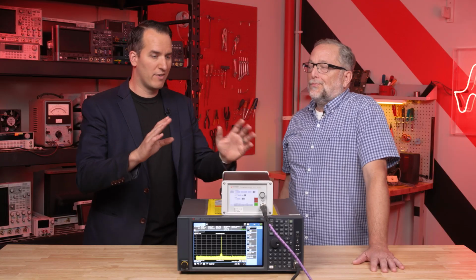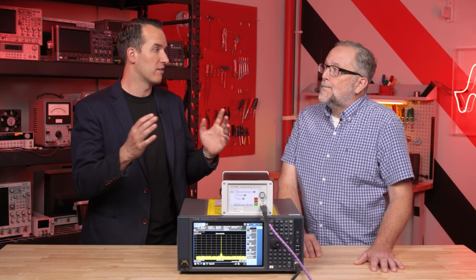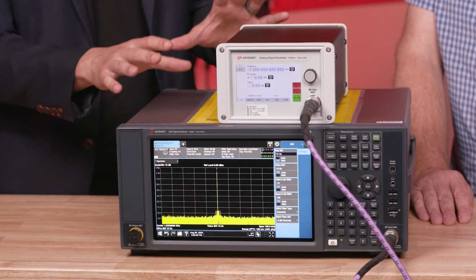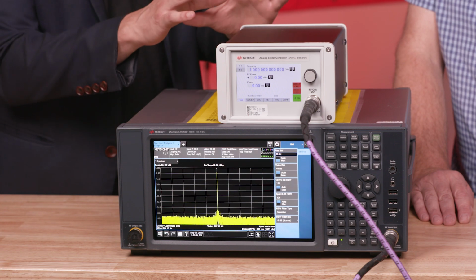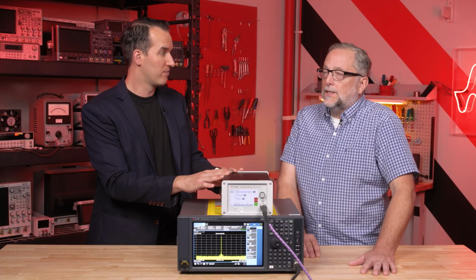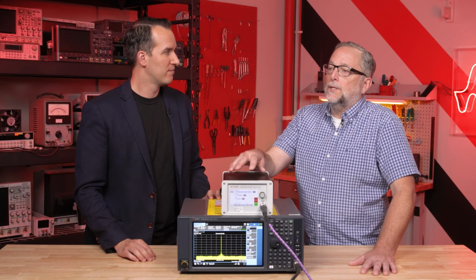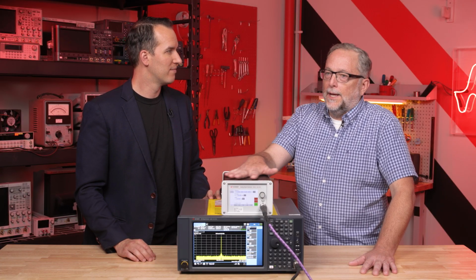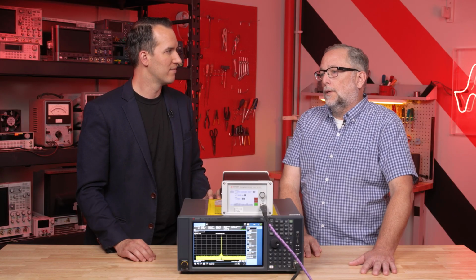And those little surprise tones can really cause issues when it comes to compliance and looking at adjacent channel power or even FCC limits. You have to know what's causing those signals and where they're coming from, and you don't want it to be your signal generator. Right. It just takes that variable out of the equation. If you can provide a very deterministic, clean, controllable source, you don't have to worry about its contribution to what you're doing, especially if you're working with low-level signals in your device test.